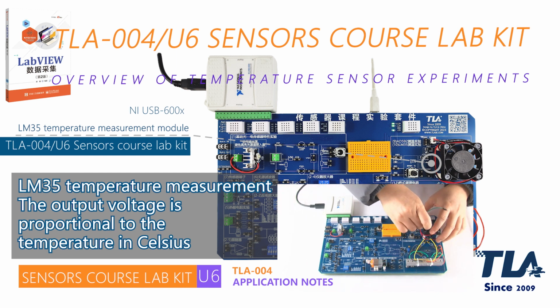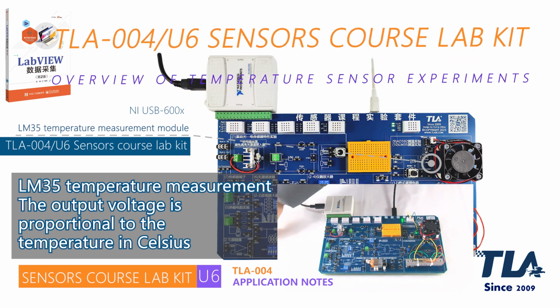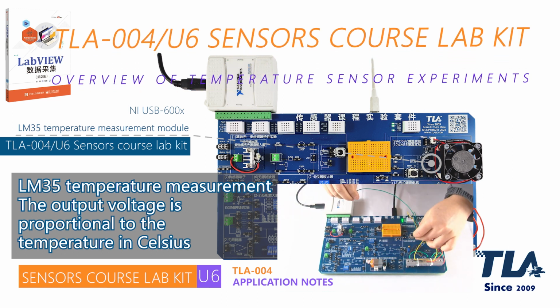Module 10 is an experimental module for temperature measurement with the integrated temperature sensor LM35. LM35 is one of the commonly used high-precision integrated temperature sensors, which is different from AD592 in that the output voltage of LM35 is linearly proportional to the temperature in Celsius.